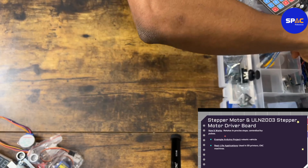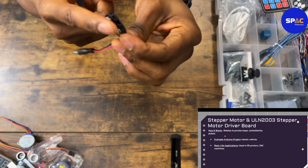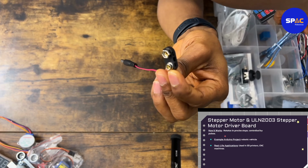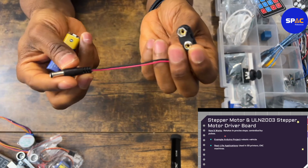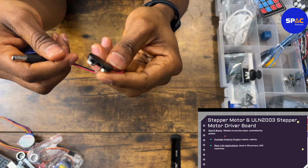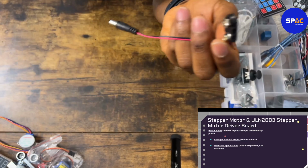And also, if you don't want to plug it to the wall, you can actually use this. This will connect to the battery that you have. I think there should be a battery somewhere. Yes, good. So you can connect this to the battery and connect this to your Arduino, right? When you are done designing everything and you want to deploy it, like say you have a robot car and you want to power it, you won't connect it to your laptop, right? So you have to connect it to a battery for it to move. So this is what you use for that.